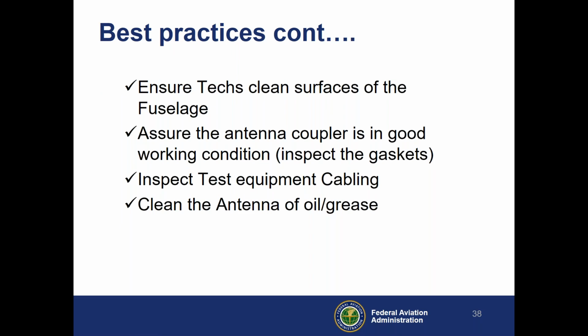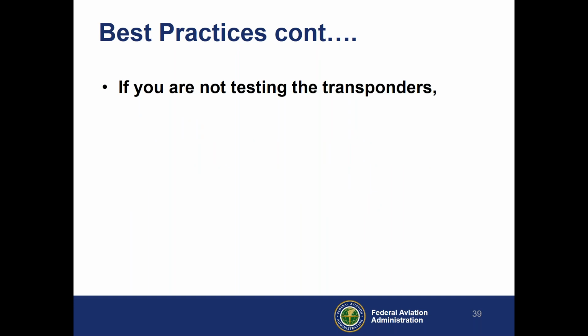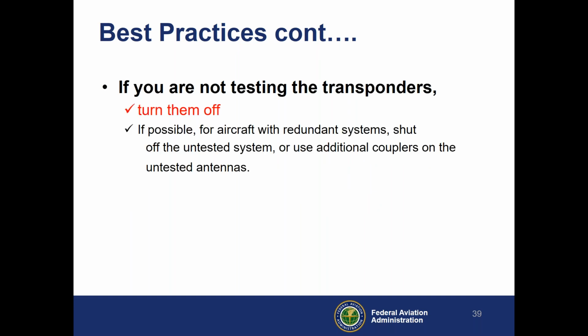Make sure that the technicians clean the surfaces of the fuselage. Make sure the antenna coupler is in good condition, especially the gaskets. Inspect test equipment cabling. Clean the antenna of oil and grease. And if you're not testing the transponders, turn them off.